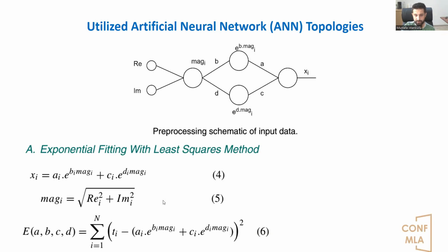Here, a measurement system utilizing artificial neural networks is presented to obtain high precision impedance measurement by using AD5933 with a single fixed calibration resistance. The ANN-based solution to estimate the high accuracy impedance value includes a unique ANN topology, artificial neural network topology. The topology consists of generally two main parts.